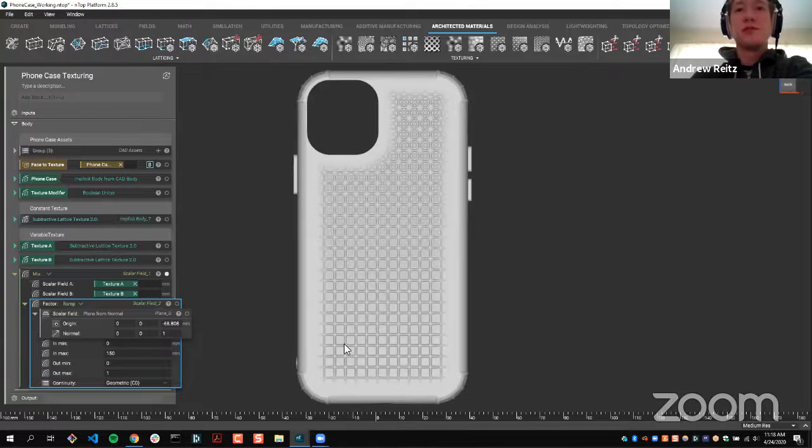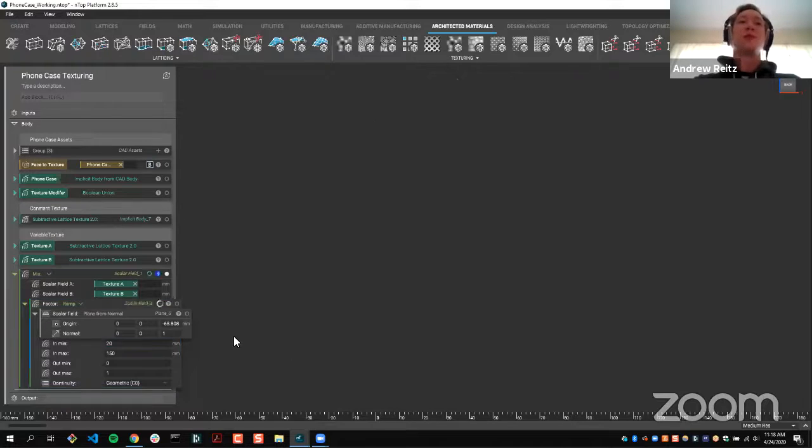Nice. This is looking really good. We can see that at the bottom here, we have texture A. And then as we gradually move up towards the camera, we get texture B. And again, I want to control this a little bit more. I just want this region to be purely texture A. So I can modify the ramp function to say, hey, this transition should start maybe 20 millimeters away from the plane. So I know that between 0 and 20 is going to be texture A. And let's say anything beyond 130, up to 150, we're going to have texture B.